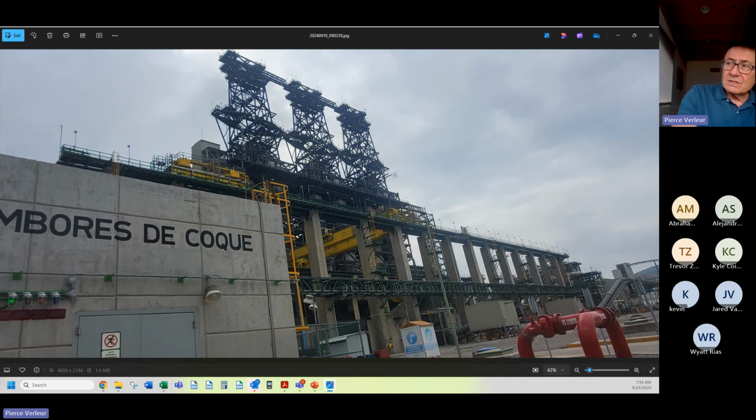Now, we did the winches that carry the water jet up and down. We also did the motion on the rotary joint, which is where we divert the water to the direction that we want. That was a very interesting application because we didn't have a lot of room. And what we did is we stuck a Yaskawa servo motor on the rotary joint that turns the water jet around 360 degrees. And the rotary joint itself is very interesting because obviously there's a seal there that allows the water to turn 90 degrees and go out the jet.